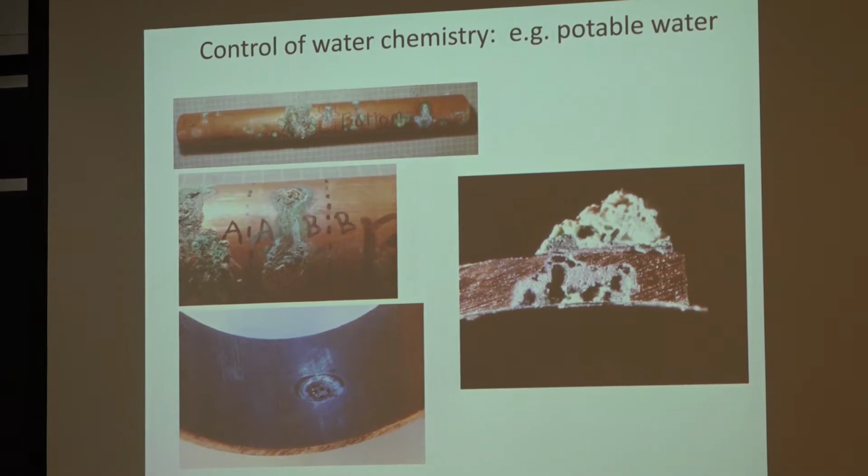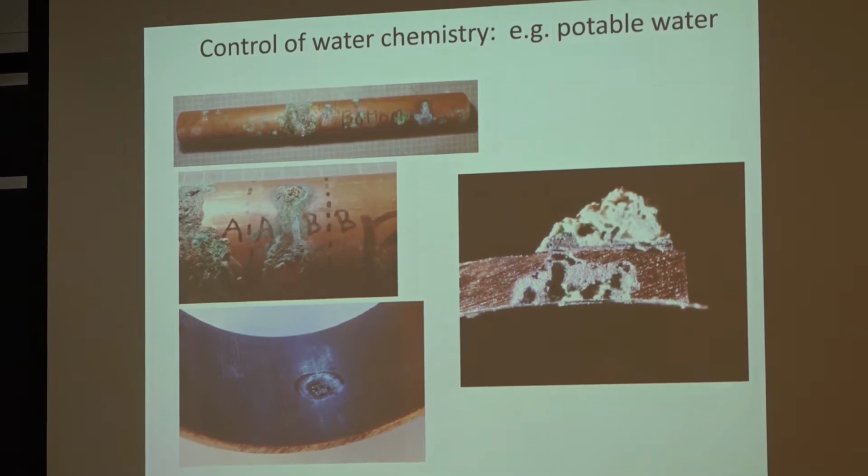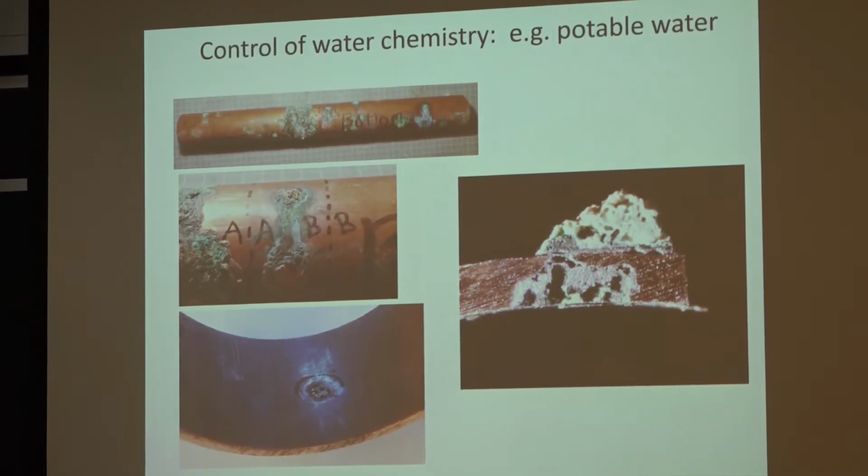Those 3 alloys or metals don't corrode significantly in atmospheric conditions, except when you have this sort of battery effect where you have a deposit, in this case on the inside of the pipe, making the environment very different there, and then creating enough driving force to initiate and pursue this local corrosion. And one thing that is interesting with pitting corrosion is you'll go with the microscope after the fact and say, oh, there is a lot of chlorides in this area, so it must be because there was a deposit of chloride here.